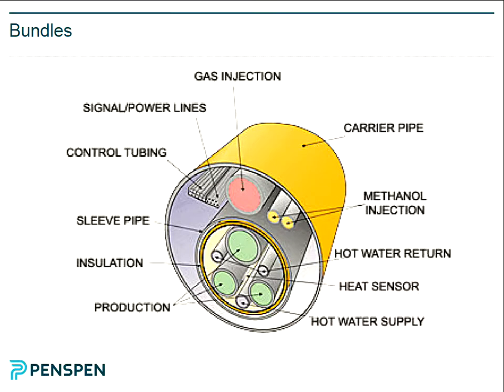Would the carrier pipe be watertight, or would it just be a protective barrier around? The carrier pipe is actually an integral part of the structure because it resists the very high axial load produced by the pipelines, potentially at high temperatures. And it's full of air during the installation process, so it's like a composite structure. So it does take quite a lot of stress, and then they sink it, and it is lowered to the seabed and flooded basically.